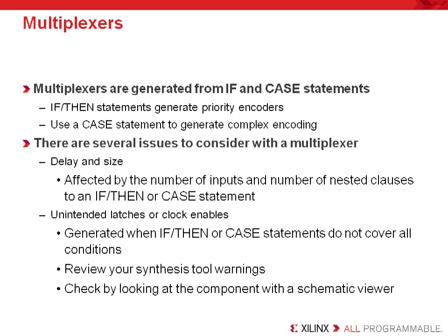You may have also heard that unintended latches or complex clock-enable equations can be synthesized when your if-then or case statements do not cover all possible conditions. Now, fortunately, synthesis tools warn users when they are building latches, but they do not warn when the long clock-enable equations are being built. That is why it is important that you verify for yourself what is being synthesized by your HDL. To do this, the best tools provide schematic viewers that show when this is happening.